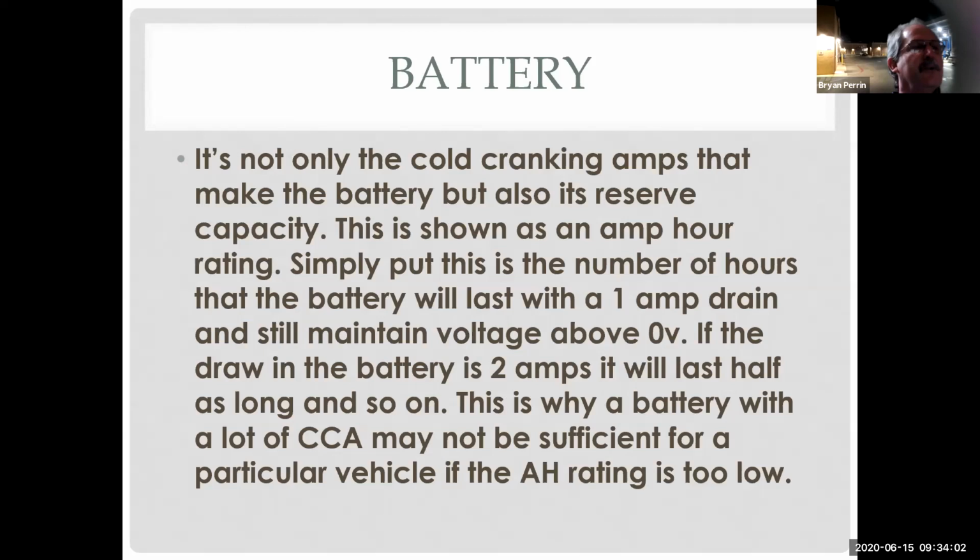But it's not only the cold cranking amps that make up a battery, but also its reserve capacity. And we see this a lot on European vehicles. Reserve capacity is the ability of a car to sit there with electrical loads on the battery for an extended period of time. So I may have plenty of juice to start the car, but if you leave me for 2 weeks, I'm dead because I don't have enough reserve capacity.